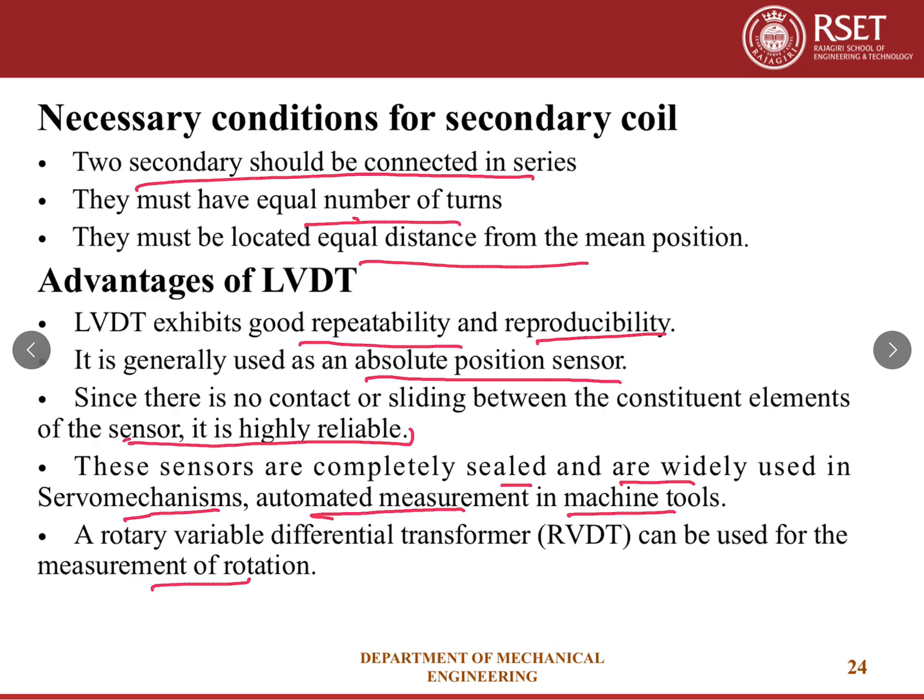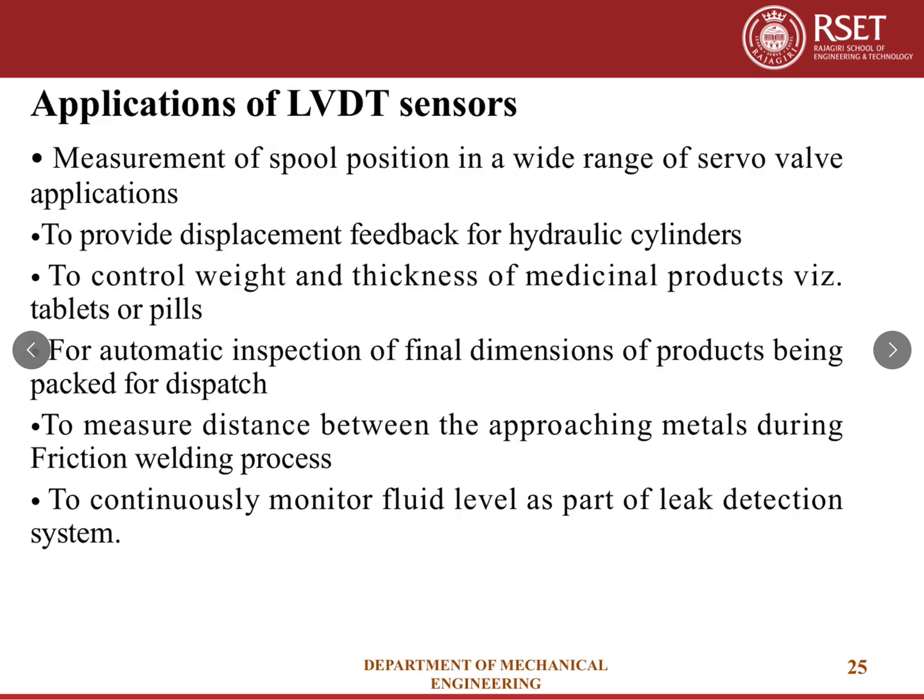Applications of LVDT: measurement of spool position in a wide range of servo valve applications. It provides displacement feedback for hydraulic cylinders. It can be used to control the weight and thickness of medicinal products, tablets, pills, etc. It is used for automatic inspection of the final displacement of products being packed for dispatch.